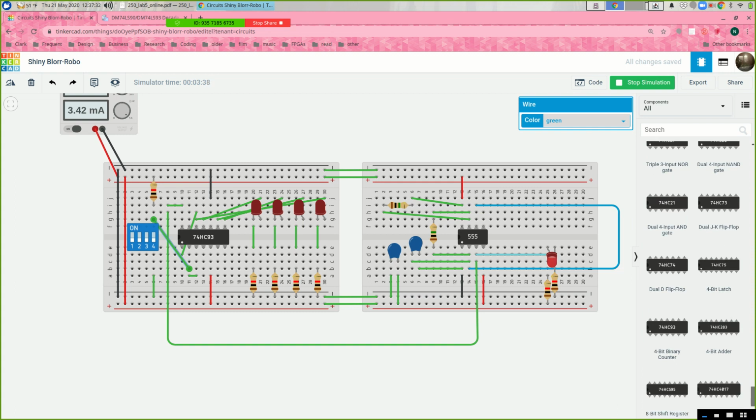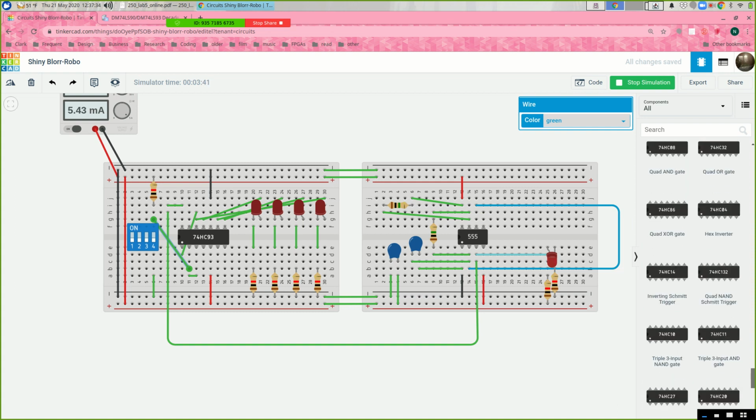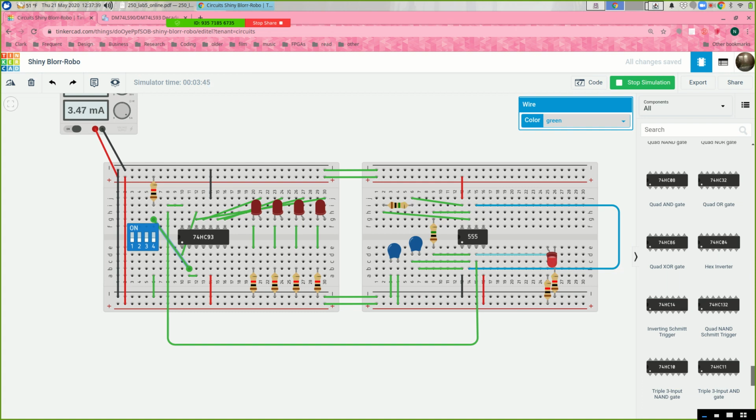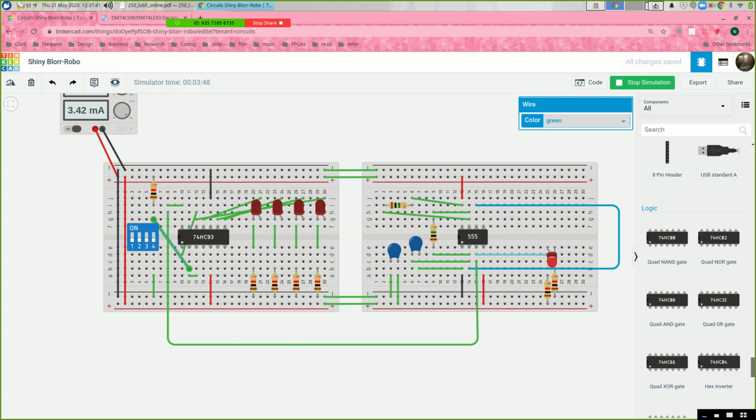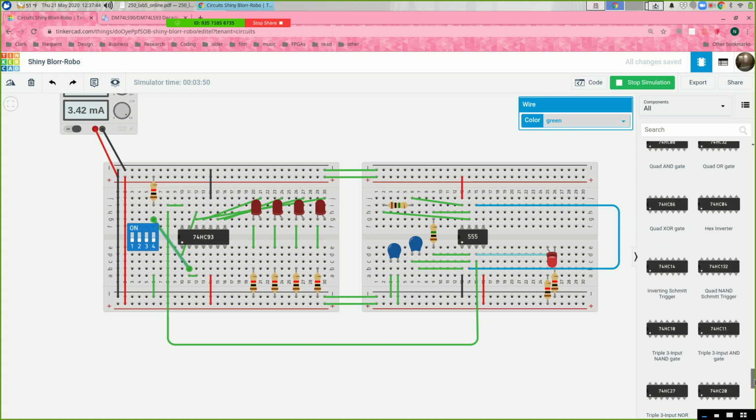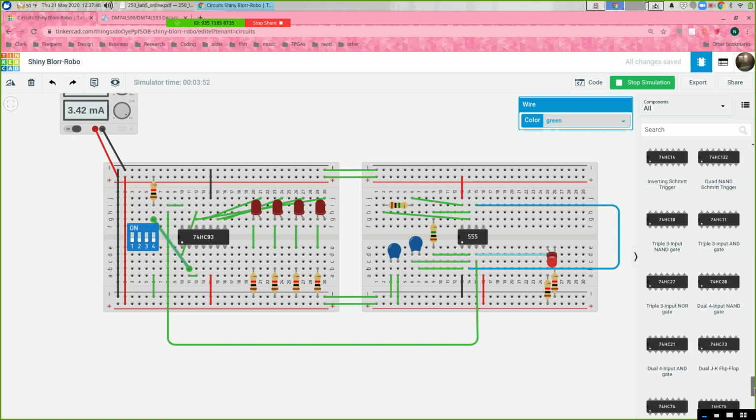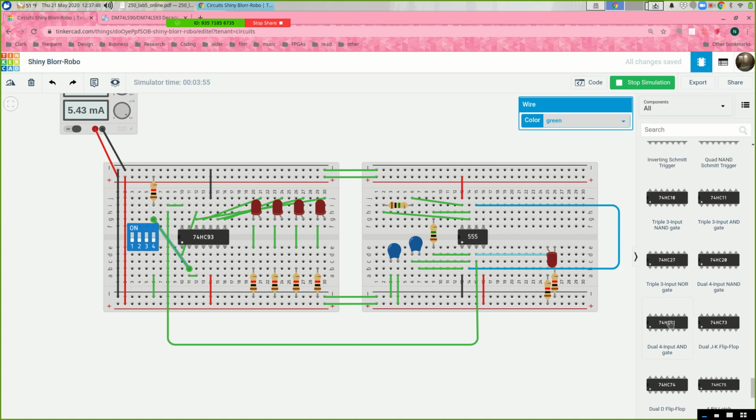So I won't build that here, but get yourself a 4-bit AND gate or a couple of 3 input AND gates and put them together. Because I don't think you have a 4 input AND. Oh, you do. You have a 4 input AND. So you'll need that. You'll need a 7404 to invert 2 of your output bits. So make another Proto board, right? Feed those in, and then use that to drive the clear input. And you should get a good mod 10 counter.